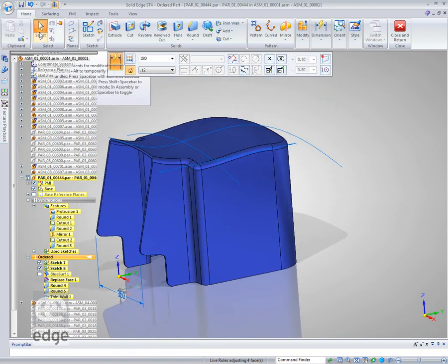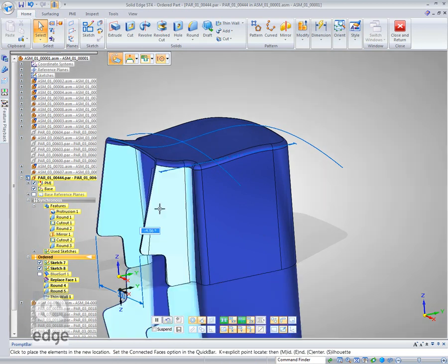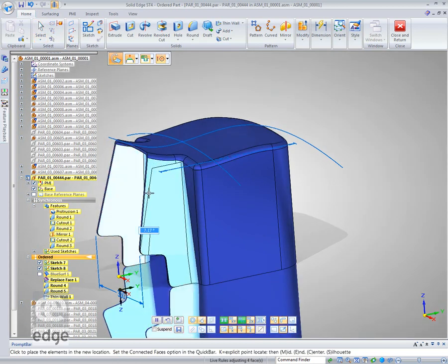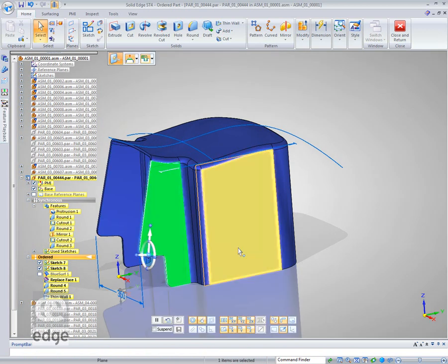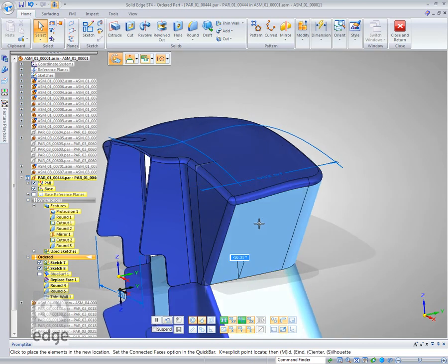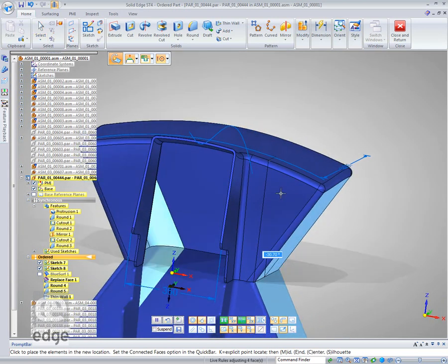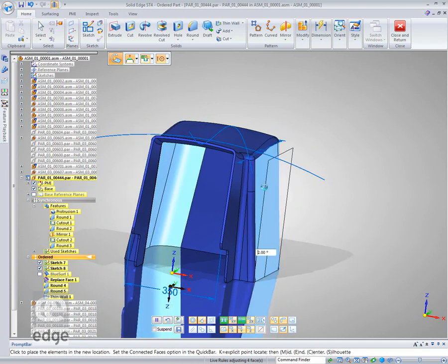We've got all our synchronous editing commands right here. So we've got a hybrid mode where we've got both ordered and synchronous together, and if I roll that in, you can see I can change that in a synchronous manner. The surface informational updates, everything works as we'd expect. I'll make that 2 degrees, and likewise with this one here I'll bring that in 2 degrees as well, so you can see the effect of that. Pull that into 2 degrees.